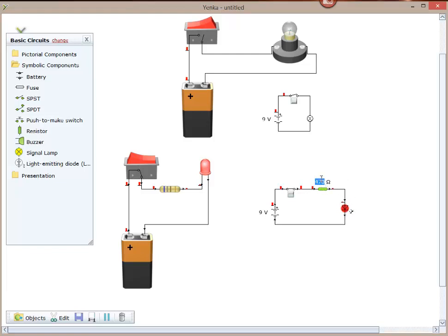Let's turn that up to a 1000 ohm resistor and see what happens to our LED. You see the amount of current diminishes, the amount of brightness diminishes. It's beginning to have an impact. 1000 ohms are beginning to prevent enough power. So we've only got 7.11 milliamps there. Let's reduce that down again to 470.